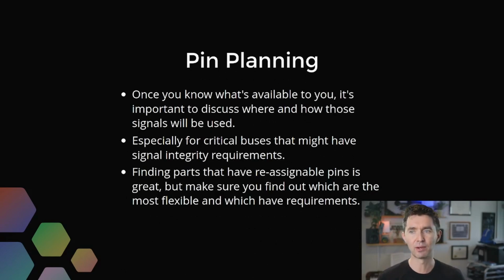Finally, pin planning, right? Once you know what's available to you, you need to actually talk about where and how those signals are going to be used, all those peripherals are going to be used. And then when you have a critical bus, right? So say you have a really important USB, you need USB 3 on your device. Well, you better make sure that you prioritize with your hardware person that these capabilities are being used on the pins, that if there's extra interrupts that are needed, maybe there's external parts that they have to interface to, but really just thinking about how some of the functionalities in the firmware space end up impacting back to the hardware space.